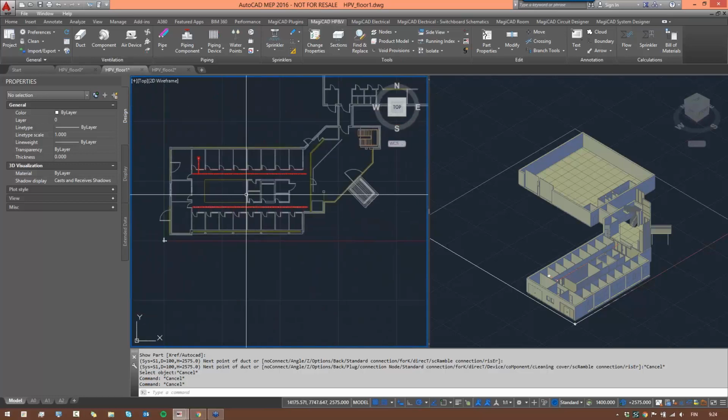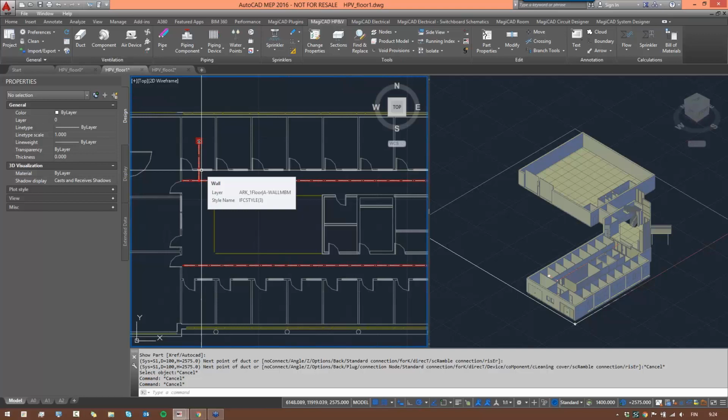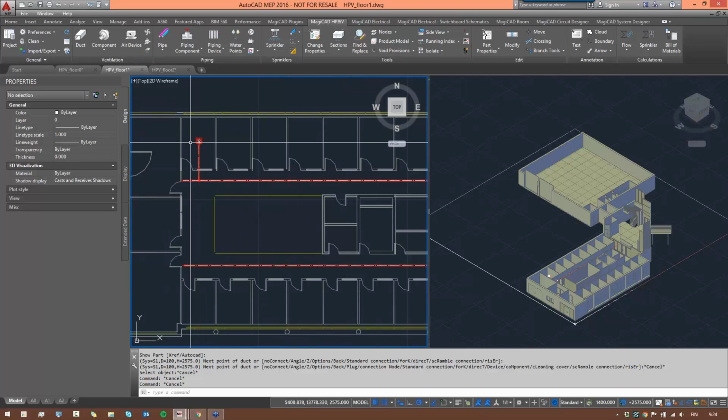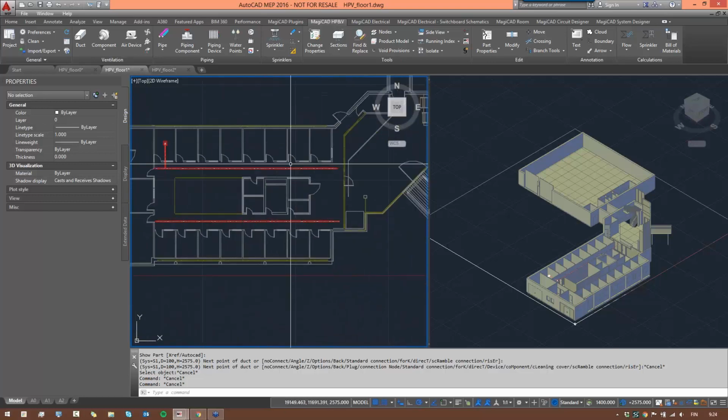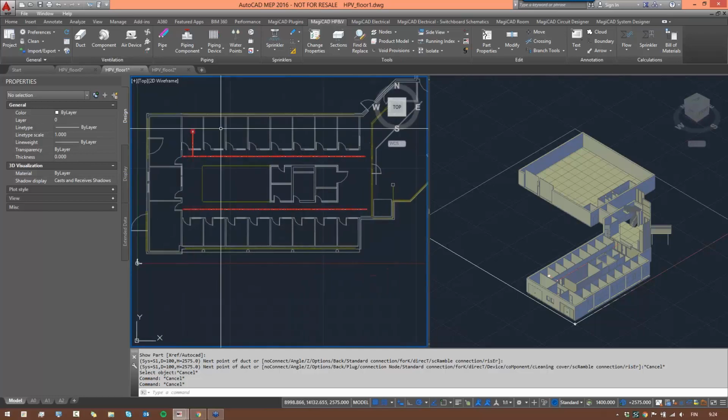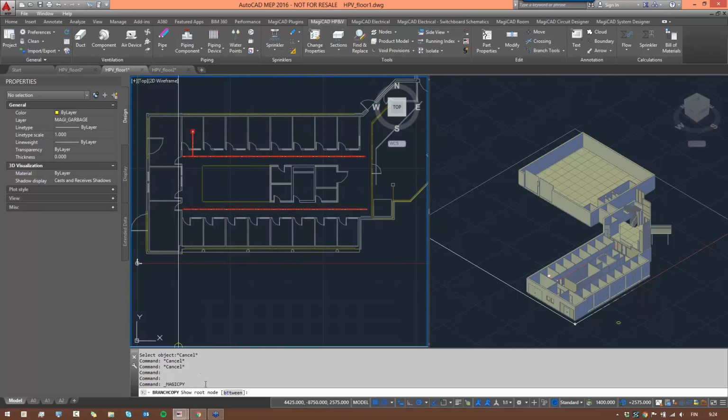Then, as I said, we could install all the devices one at a time, or if they're the same size offices, they have the same airflow in there, we can just use a copy tool. Instead of using just AutoCAD copy functions, we've added our own tool here, which is called a branch copy, which means that now that I started, first it asks us for a root node.